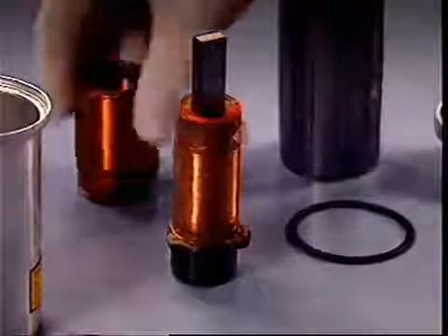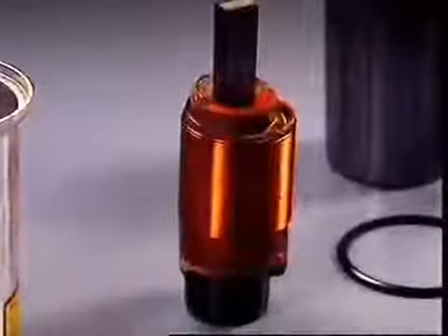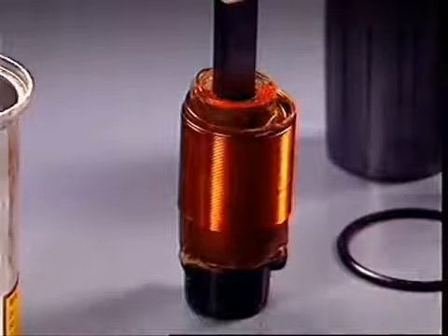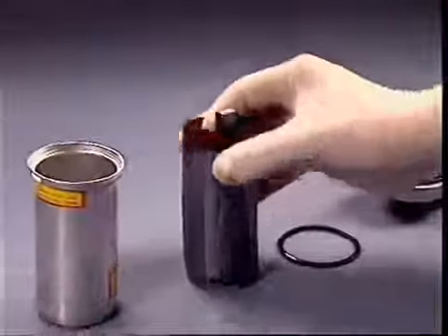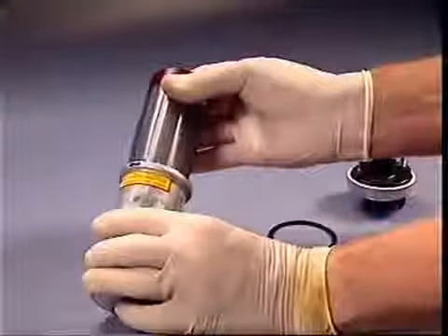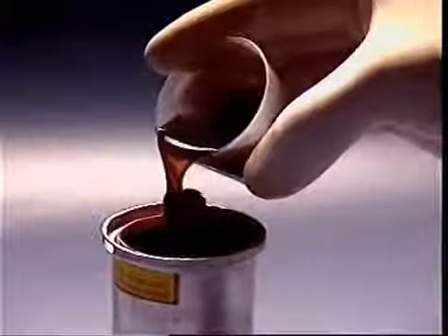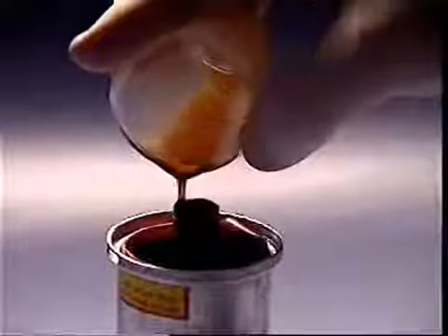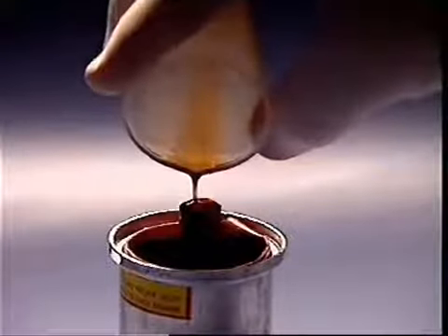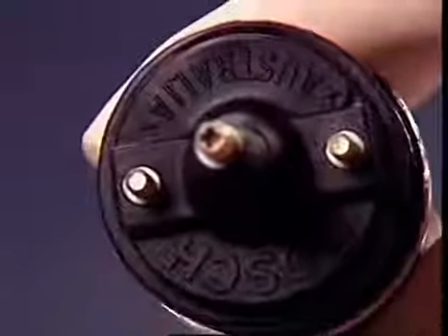The primary winding, with a few hundred turns of much heavier copper wire, is wound on the outside of the secondary. A shield of soft iron surrounds the outer windings and the complete assembly is inserted into a one-piece steel or aluminium container. The container is then filled with a special transformer oil, which provides good electrical insulation and also permits rapid heat dissipation. The cap has two terminals, positive and negative, for external connection to the primary circuit.